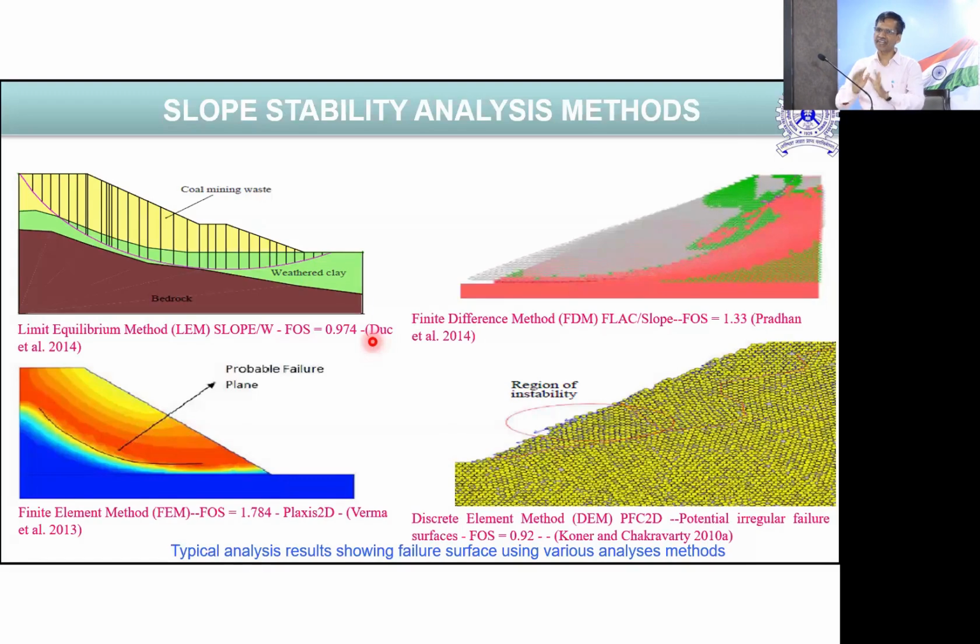In an embankment we consider a certain load, 1 or 2 kilonewtons per square meter as vehicle load. Otherwise, most of the time we assume this is self-weight and we are analyzing that it should be stable, particularly in arch dikes or tailing dams. When the moment of resistance is to be increased, that depends upon the sliding plane, how much it is. Does this only occur on the downstream side slope? No, you have to check both sides.